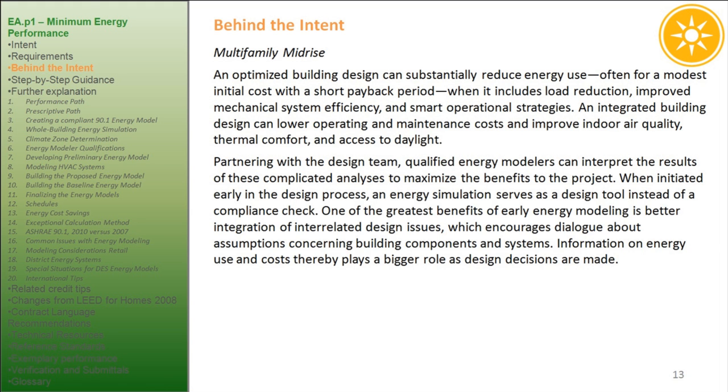Partnering with the design team, qualified energy modelers can interpret the results of these complicated analyses to maximize the benefits to the project. When initiated early in the design process, an energy simulation serves as a design tool instead of a compliance check. One of the greatest benefits of early energy modeling is better integration of interrelated design issues, which encourages dialogue about assumptions concerning building components and systems. Information on energy use and costs thereby plays a bigger role as design decisions are made.